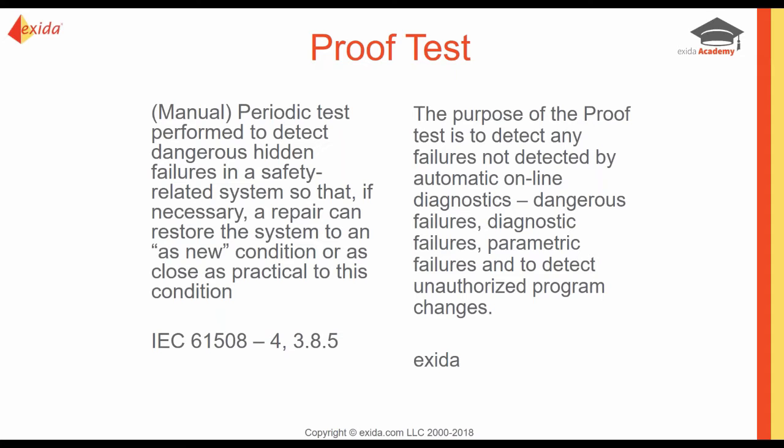We're going to talk more about how to make your best proof test coming up. But because proof testing is such an important part of your SIFs and your SISs, we're going to look at the reasons why. IEC 61508 and IEC 61511 actually require proof tests, and the more they require it, the more end users are implementing proof tests. But with more people implementing proof tests, there is more confusion on when to do it, what coverage, your efficiency, and what can be claimed for your proof test. So we're going to look at all of that today.